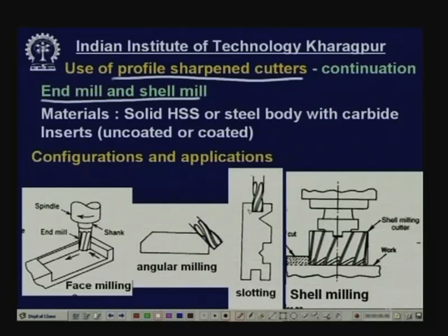So there is a jerk or vibration, and therefore the cutting tool material should be tough enough, and high speed steel is very tough. And the geometry of milling cutters is very complex, and manufacturing is very difficult. High speed steel can be easily formed by forging, rolling, machining, heat treatment and grinding, and it is very tough and strong. So most milling cutters are made of high speed steel, but sometimes carbides are also used, either brazed or as sintered carbides that are clamped, and if clamped it can be uncoated carbide or coated with titanium carbide, titanium nitride, etc.